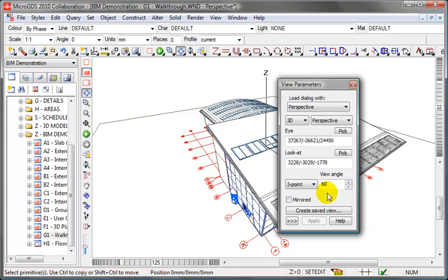effect of the design. You don't want to be doing that too drastically, because if you actually use a field of view that makes a space look larger than it really is, you can be conveying the wrong impression to your client. And you can create a new saved view from the values that you enter here if you wish, or from the values that you've already got as a starting point.